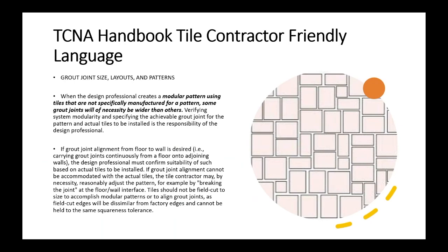If you buy a Versailles pattern or a herringbone pattern, those types of things that are intended for that purpose, that's one thing. But if you're going to buy different tiles of all things by different manufacturers and expect them to fit together in a nice pattern, the odds are very slim that those grout joints are going to be the same size.